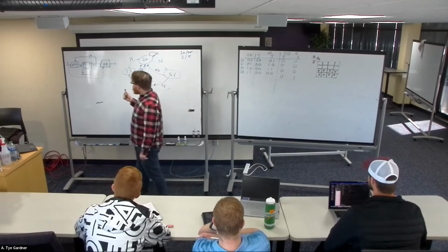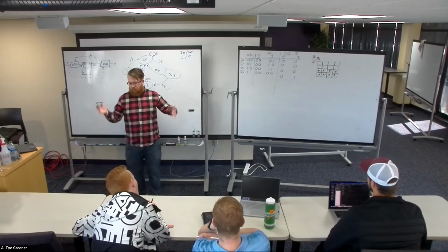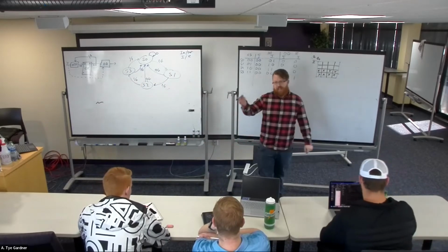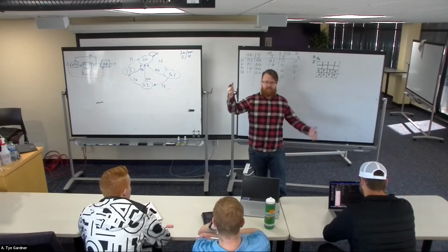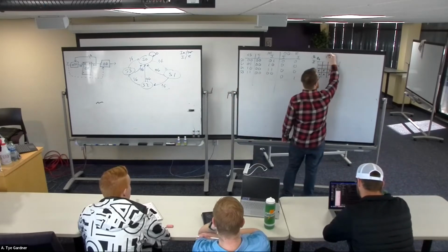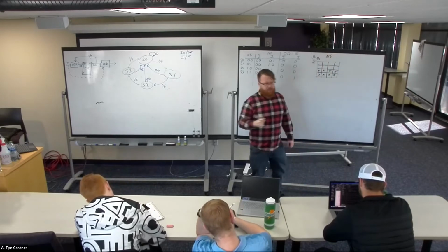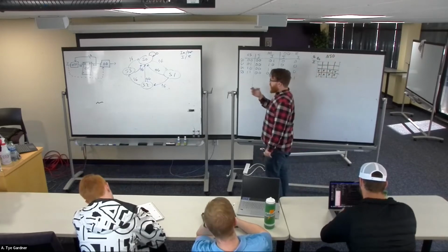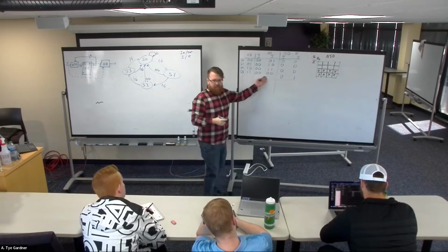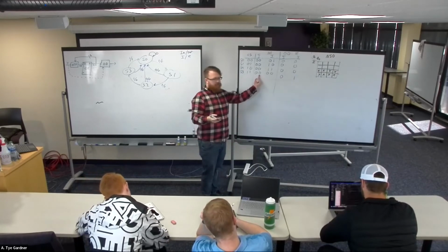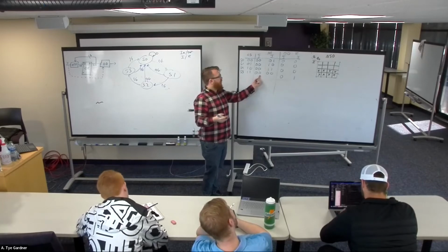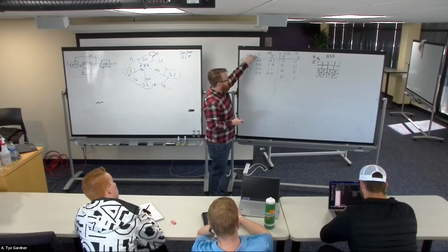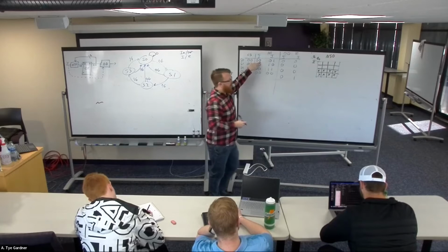Okay, so then we look at it and say, where do we pull the K-map values from? Well, I need to decide what I'm designing, right? The next state has to have 2 bits because the current state has 2 bits. So the states have 2 bits. So let's design the first bit of the next state output. So NS0, next state 0, being, this is my next state column of the table. It's these, right? So this says that when I'm in state 0 and I have not 0, it has a 0. That's this square.